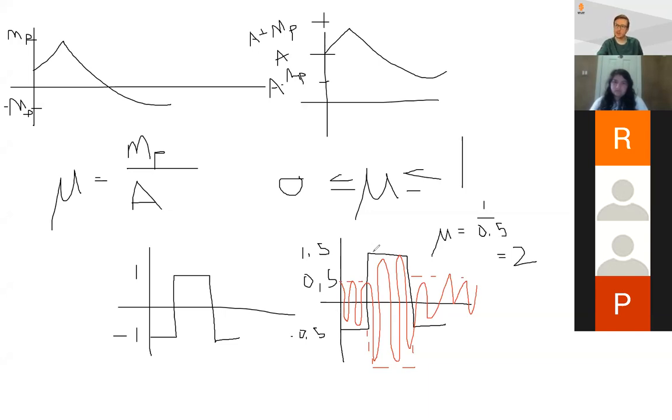If this was an analog message, you might be a lot more out of luck here. But for a digital message, you could still put this through an envelope detector. The envelope is still going to look like this, which is basically the shape of the original message, but it has been distorted because the pulse is much weaker than it was in the original message.